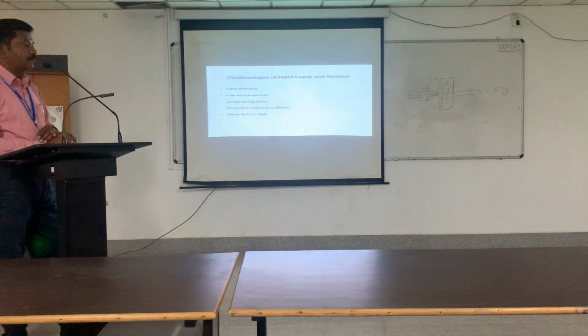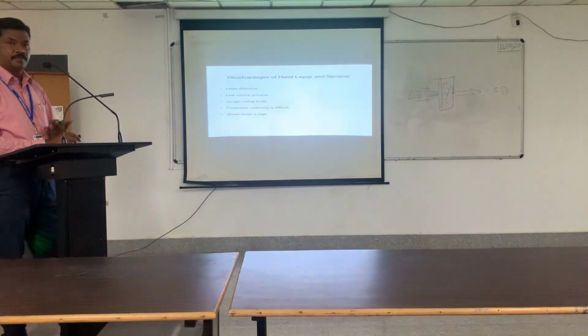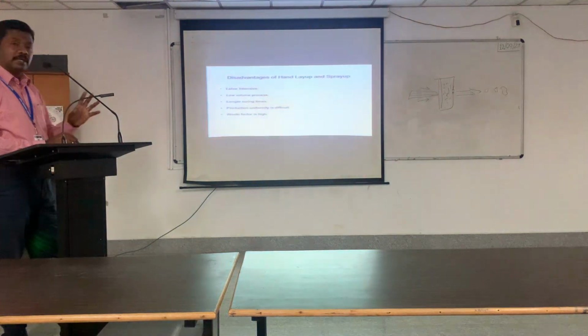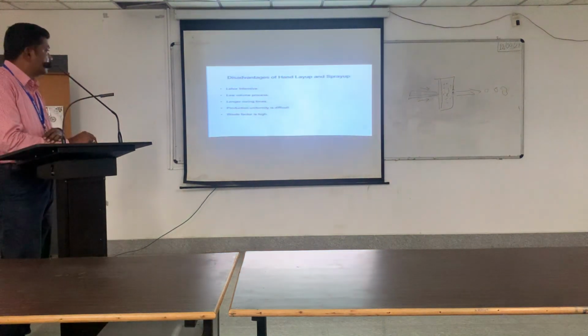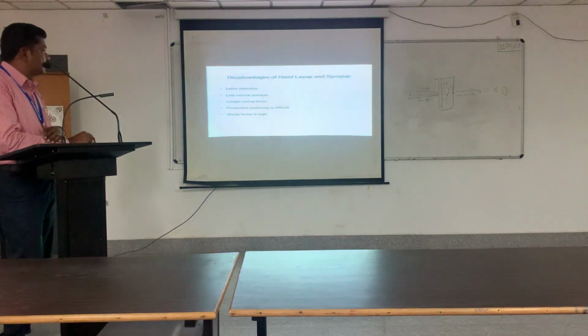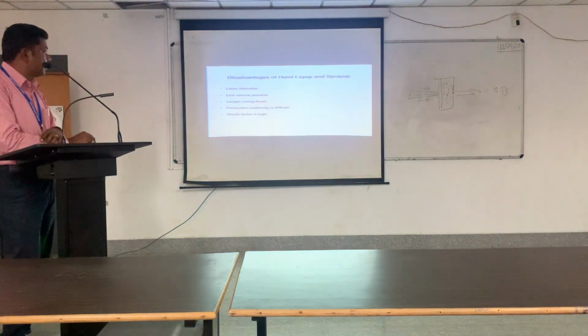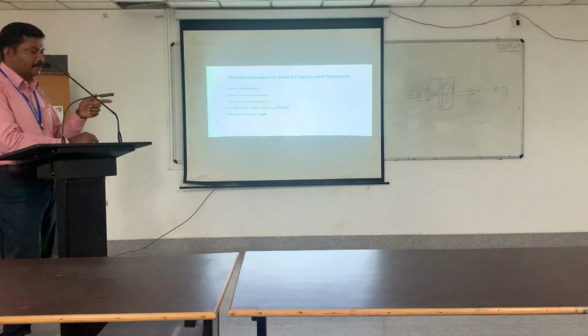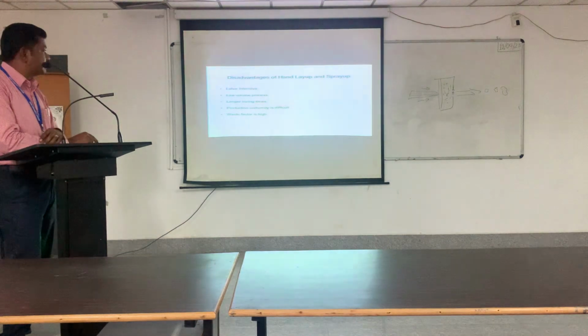Disadvantages in both cases: labor intensive, low volume process, longer curing times. If you add more accelerator in the gun itself, sometimes it will get cured there. So you cannot add more accelerator either. Since the processing requires some amount of time, the curing time is higher. Production uniformity is difficult; that is the consistency. Uniformity will not be there. Waste factor is high. Even in the spray process, some amount of the material will be sprayed out. The waste factor is high.